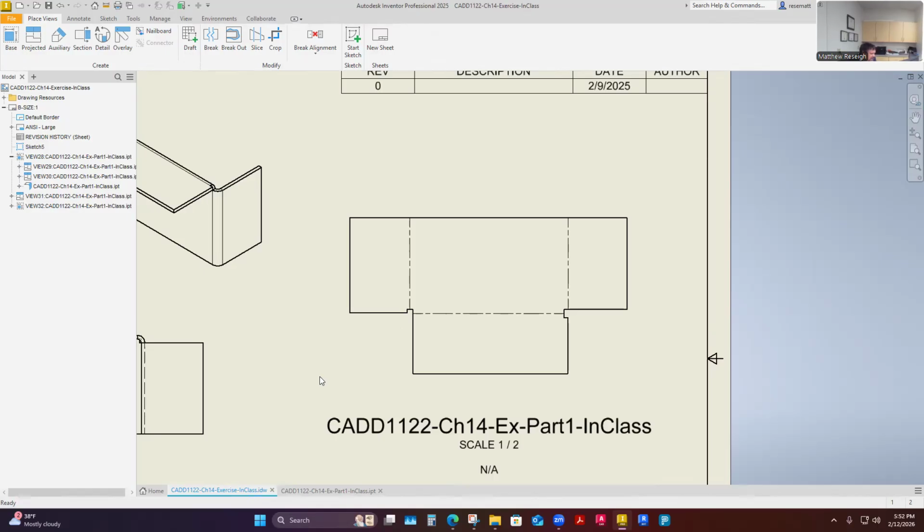And so they can identify the parts, but you can help them identify the parts because maybe they don't have the whole print pack. They're not the ones building the equipment. They're just the ones cutting the parts, so they're just looking at cut file sheets a lot. It helps them to have the part identification. They can even choose on a laser to etch that part number on the part. They could even just steal your part number description here, throw it on here, size it down, and have that etched on there.